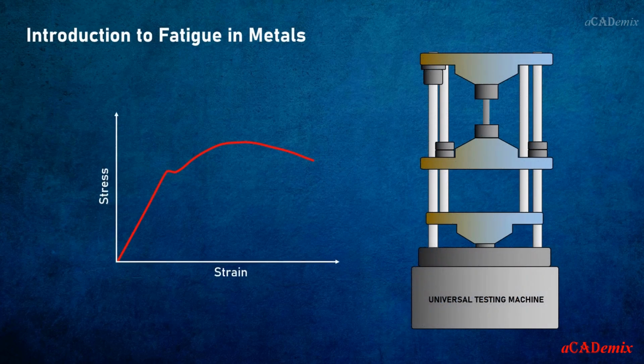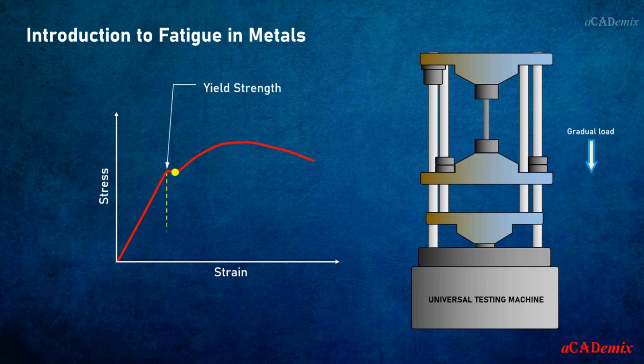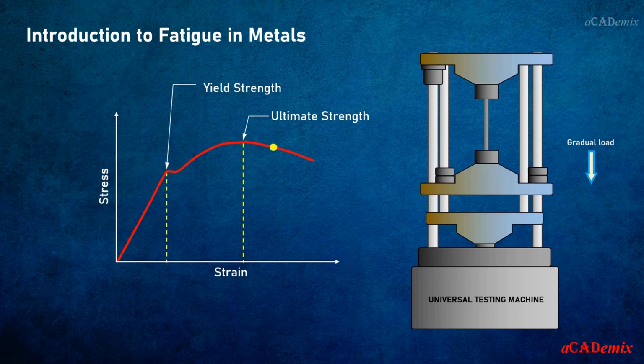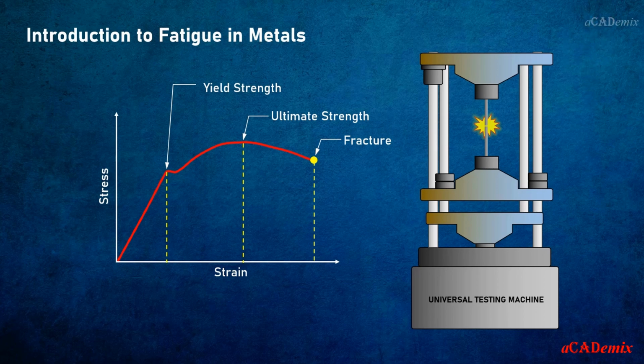In most material testing procedures, the load is applied in a gradual manner, because in order to get the material properties related to the stress-strain diagram, it is necessary to give enough time for the strain to fully develop. Here, the specimen is undergoing a destructive test. That means the stresses are only applied once. The condition for this type of testing is called static condition.